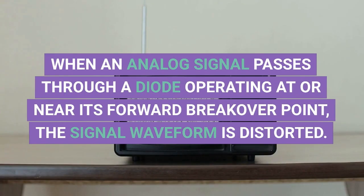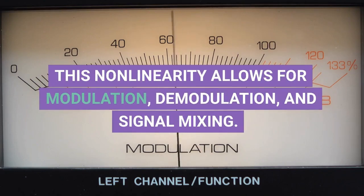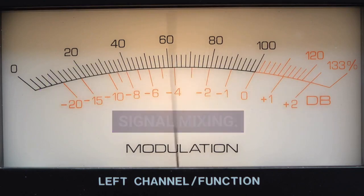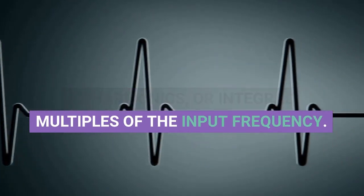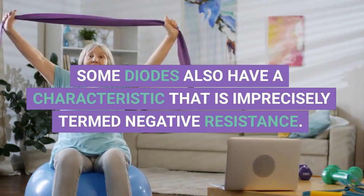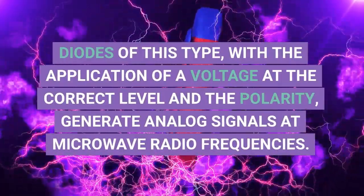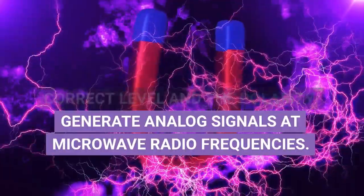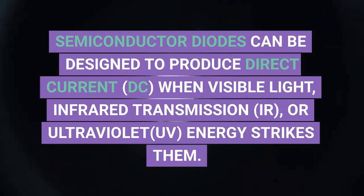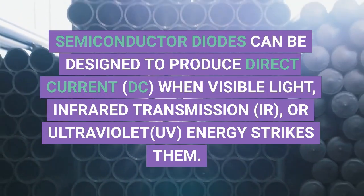When an analog signal passes through a diode operating at or near its forward breakover point, the signal waveform is distorted. This nonlinearity allows for modulation, demodulation, and signal mixing. In addition, signals are generated at harmonics, or integral multiples of the input frequency. Some diodes also have a characteristic that is imprecisely termed negative resistance. Diodes of this type, with the application of a voltage at the correct level and polarity, generate analog signals at microwave radio frequencies.